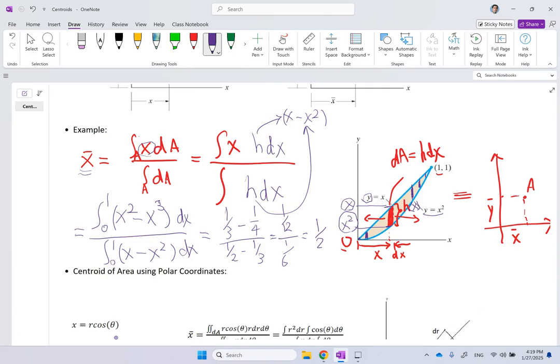So you see the x of the location of the centroid is 1/2. In the middle exactly. The x of the centroid is actually 1/2 in this case, and it is fine. Now you might say, is the y of it, y bar, also 1/2? Well, you'll find that it's not. But you see that x of the centroid is 1/2, so I can squeeze that surface down to a single point at x bar of 1/2, whatever y bar we're going to find next, and I can put all the area right into that point. So this is for x bar.